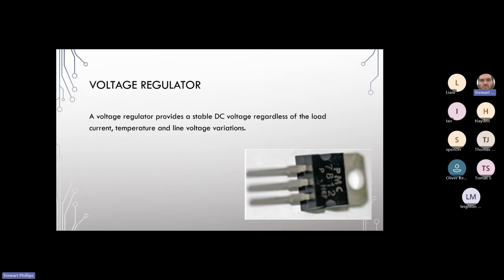The input voltage is similar. It should be anywhere from negative 27 to negative 14.5 volts. And protection circuits against short circuits and thermal overloads are incorporated into it. Safe area protection is provided for an output transistor. So to put it in perspective, the black part of that component would fit on the end of your finger. So that's the size of it.